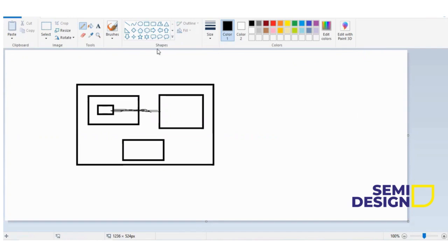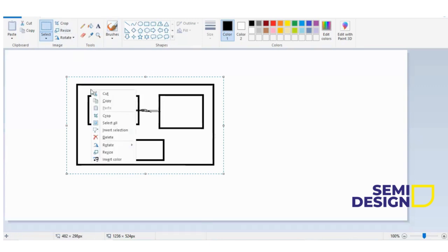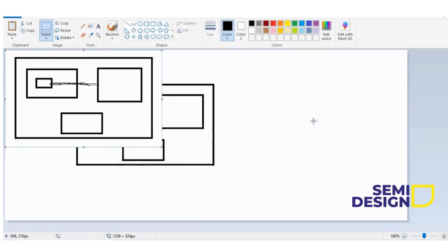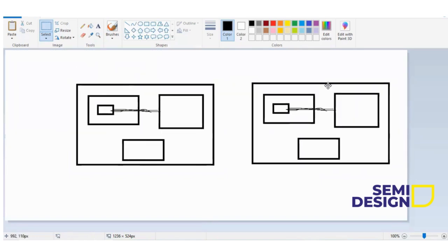So instead of again creating these things, again writing APB sequencer, again APB driver, APB monitor, then connecting APB sequence to APB driver, what I can do simply is create two instances. Okay. So now automatically everything is created. So that is the use of APB agent. It is used for reusable project purposes and it encapsulates the UVM driver, monitor, sequence.